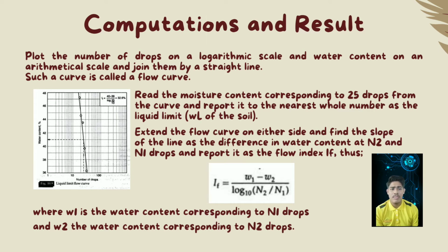Read the moisture content corresponding to 25 drops from the curve and report it to the nearest whole number as the liquid limit.